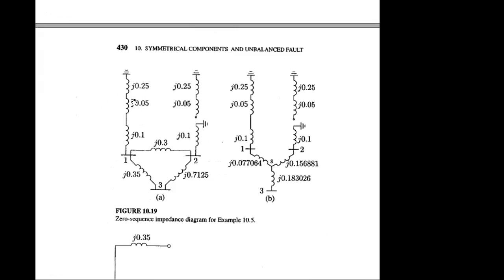When we want to put the equivalent information for all the generator transformers, here you can have transformer 1, transformer 2. Okay. Regarding transformer 2, here you have some open terminal because of the delta in the upper part. The lower part is the Y and the upper part is delta. And I have already shown the equivalent circuit for the transformer internal configuration for Y delta.